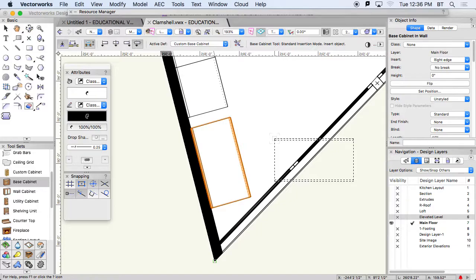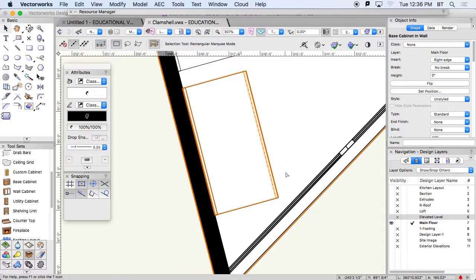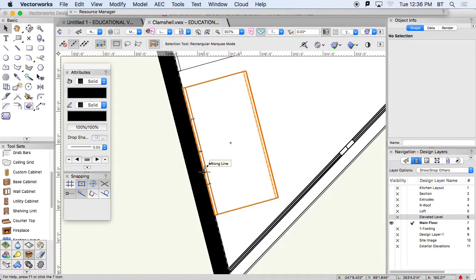Now in plan view, it's pretty simple. It shows the cabinet with the dash line and the countertop. So even right now, I can visually see that, I'm going to deselect it, there are two solid lines here, so that's representing the backsplash. You're going to see the very back edge of that backsplash, and then you're going to see that thickness, right? It's graphically representing what you're seeing. Then you're also going to see here the edge of the countertop, and below that there's going to be an overhang. That countertop is going to overhang an inch, and that cabinet is then shown in a dashed line.